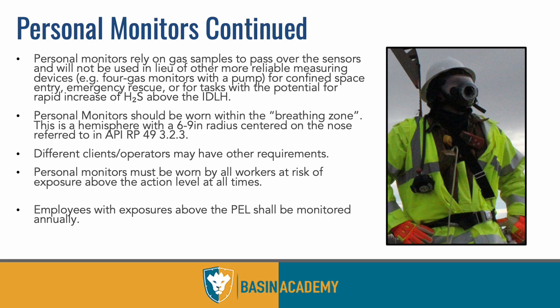So looking at them, essentially what happens is the gas passes over the sensors and it's constantly reading. It's designed to be in your breathing zone so that it's reading the air that you're breathing, and when it alerts you, it's not just saying, hey, there's H₂S around. No, there's H₂S or LEL exactly in the air that you're breathing. So this is something I should be really paying attention to. And that breathing zone is identified in RP 49 3.2.3. Not going to ask anyone to remember that, but it's a chart, and it's about 6 to 8 inches from the nose and mouth, basically in a circumference, up, down, left, right. That's where you want to have your monitor.